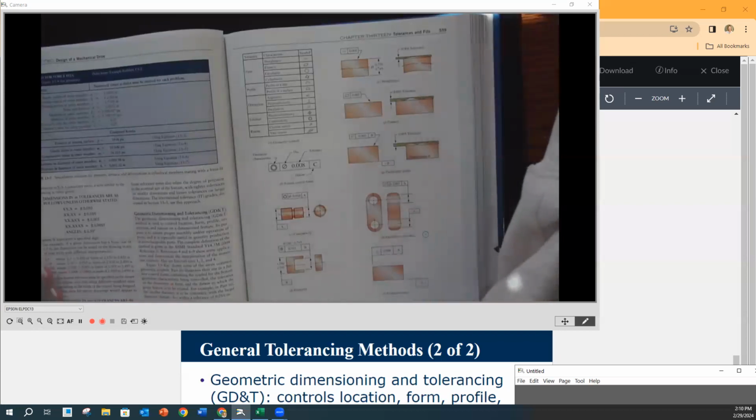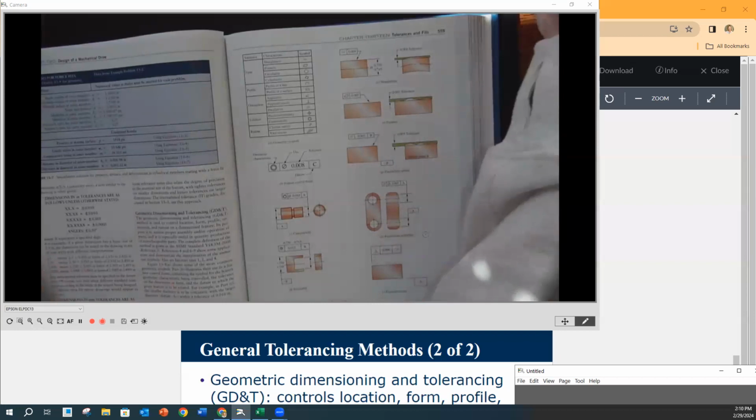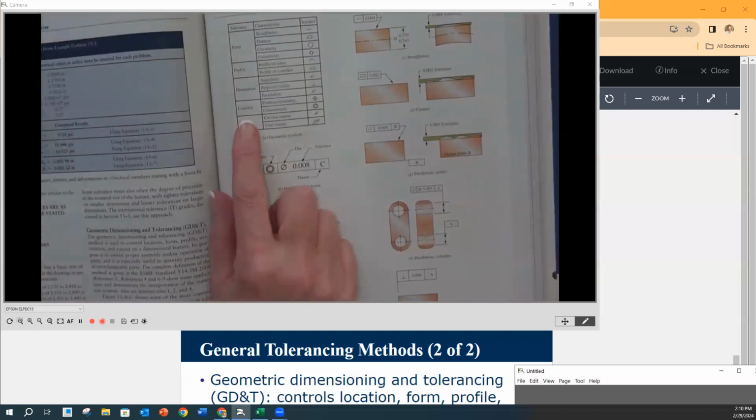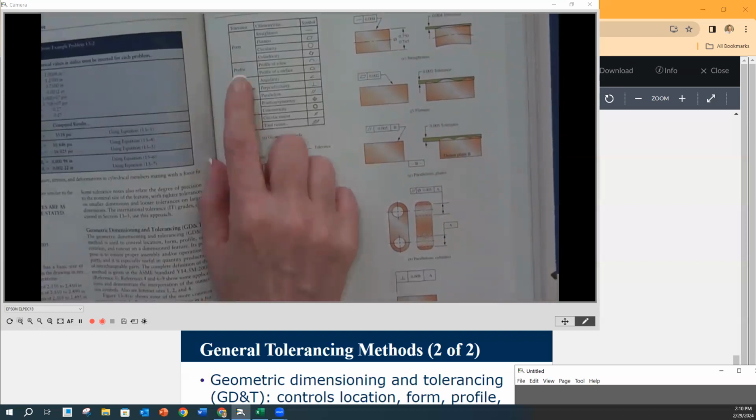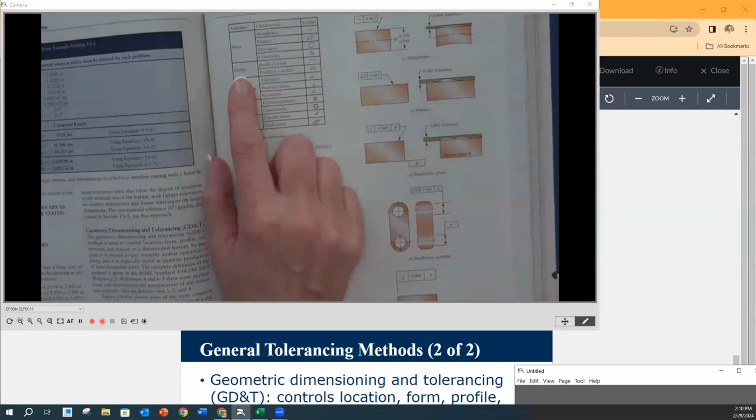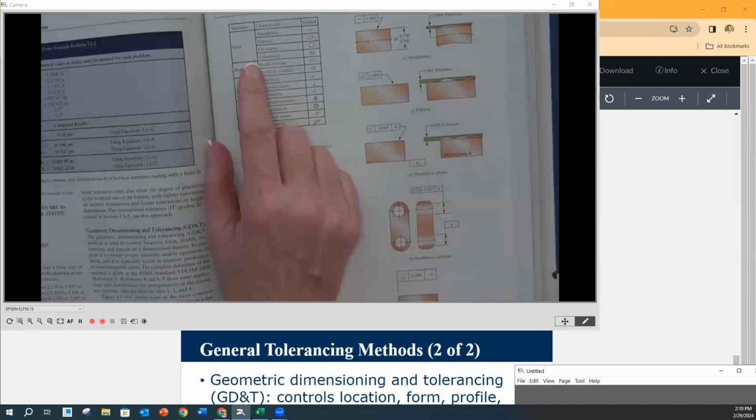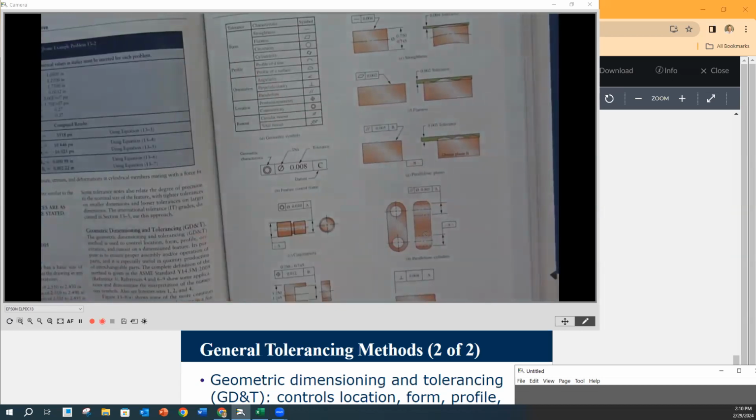So like I said, it talked a little bit about GD&T and their application. So position, location, you should be doing this all the time, all the time. Orientation, profile should be considered most of the time with sizes and the outsides of things. And then form is going to be as needed as well as a refinement of.